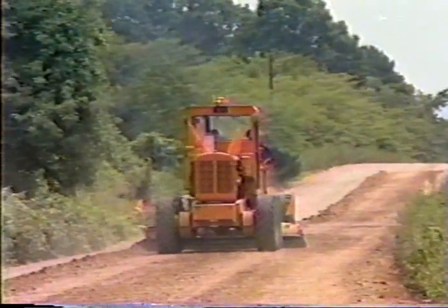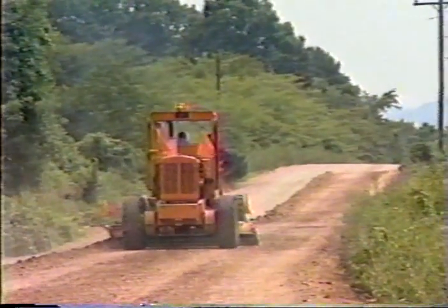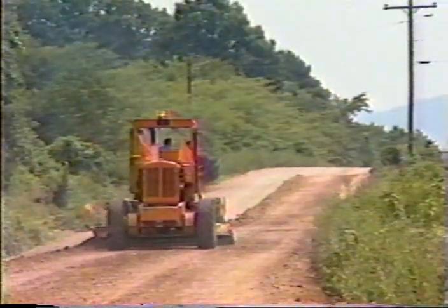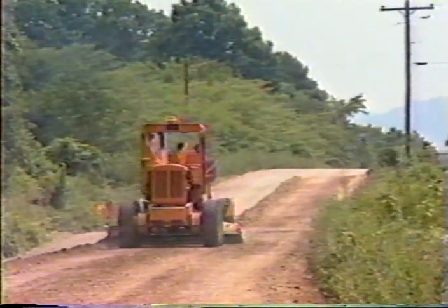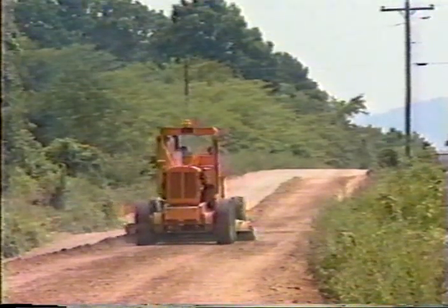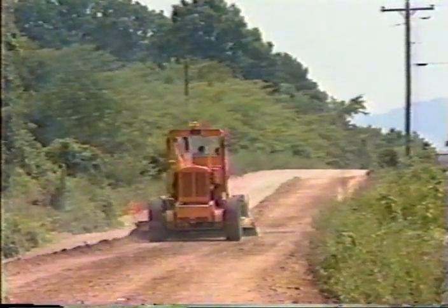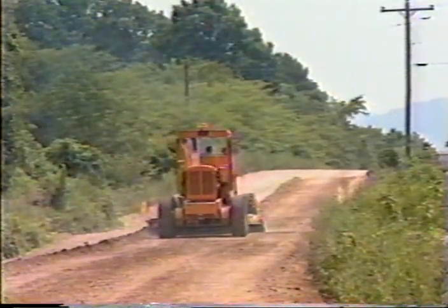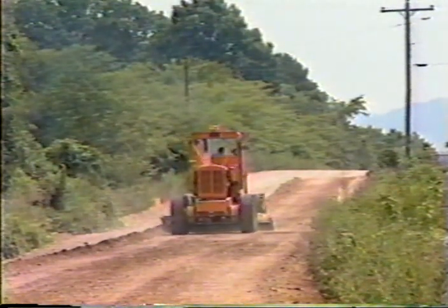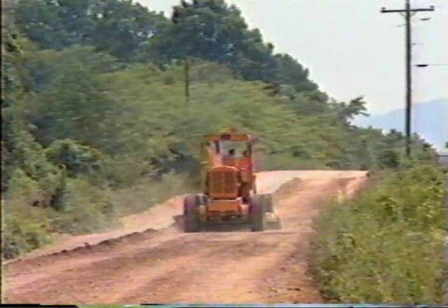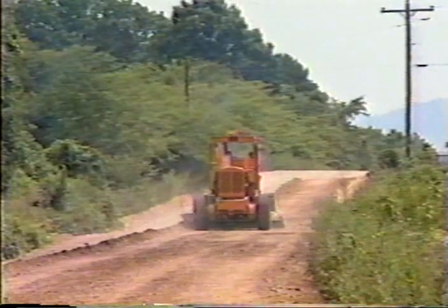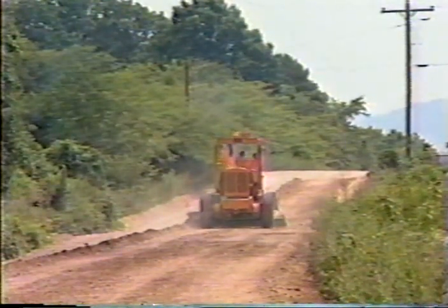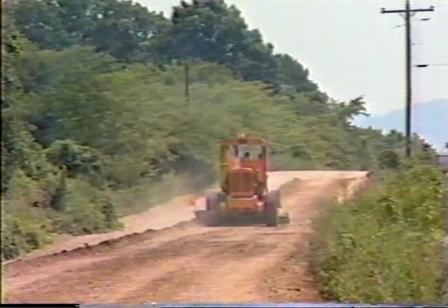With the blade set properly, smooth the roadway. A properly set blade will create a dragging, rolling action that will compact the surface as it is bladed. For most roads, a single round will be sufficient. If there is excess material in the center of the road, another pass will have to be made. Spread this material evenly, being careful not to destroy the crown of the road.